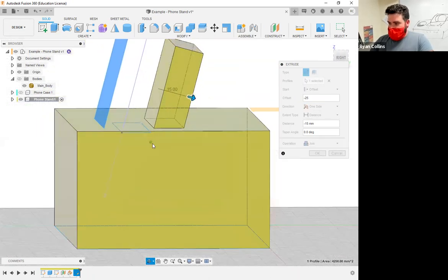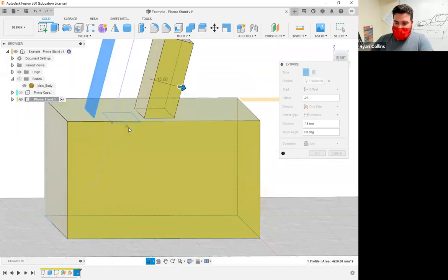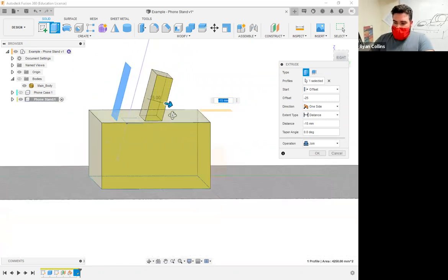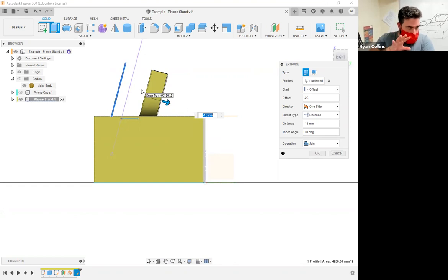I see what the problem is now for the other, why it was automatically creating a construction line. For some reason I accidentally selected that line, or when I selected that line, it's actually below the work plane I was working at. So I'll have to adjust for that. That's okay. But now creating that construction plane has allowed me to extrude at the angle that construction plane is.